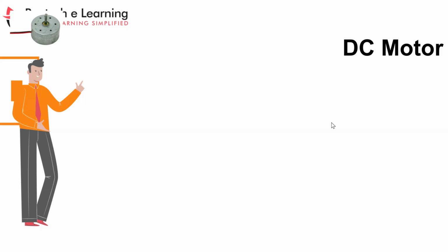Someone has asked whether an EV inner wheel or outer wheel drive is best. For two-wheelers, hub motors are used, so the outer rotor motor will be the better one. The same applies to in-wheel motor car applications: an outer rotor motor, but that is not a hub motor, it's an in-wheel motor.